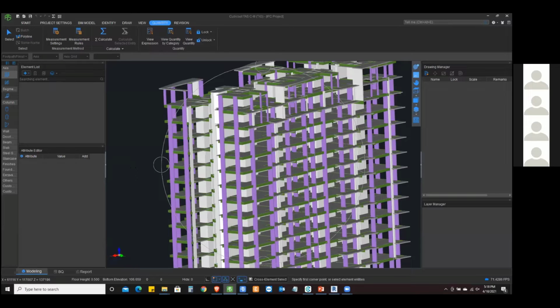Well, quantity estimation, as the QS or estimator, we tend to use different drawings. If I simply answer your question this way, if you have a drawing at a very early stage of a project, you have only the conceptual or maybe schematic design. It's just the concept or a very basic level plan, and from there you have to determine your order of cost estimate. That's a particular set of documents that you need to prepare. And then after that, you get to cost plan 1, cost plan 2. So throughout the project life cycle, you have different stages.